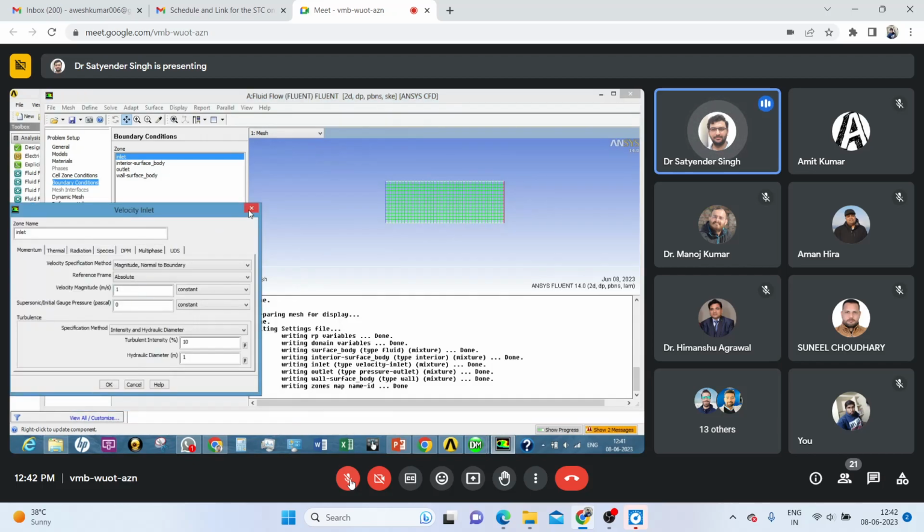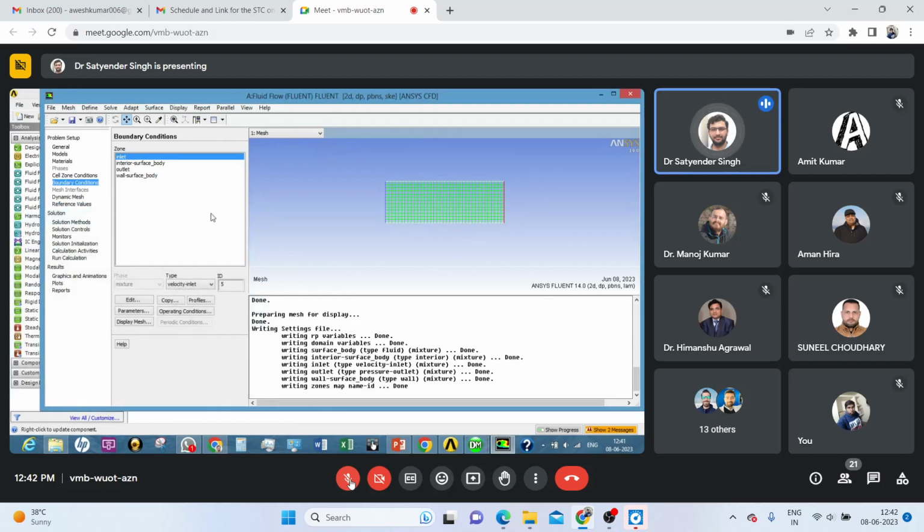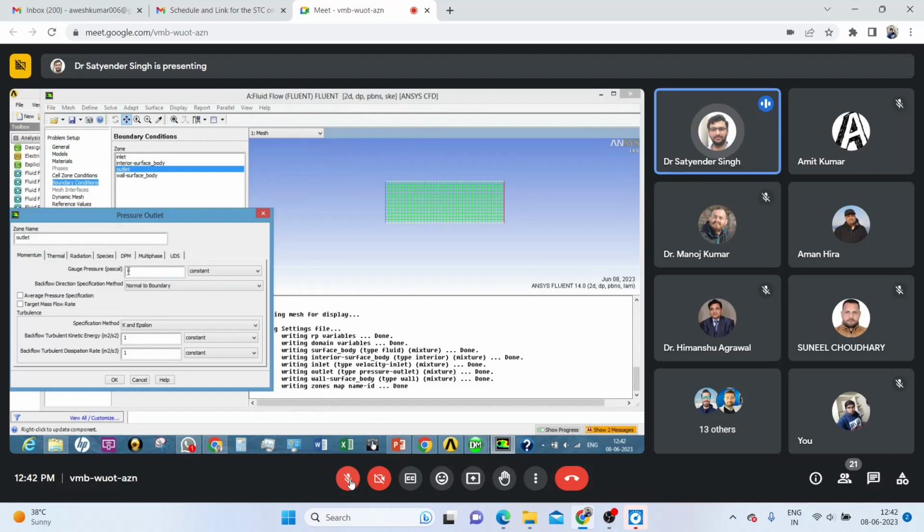We can assign value only to the velocity or in terms of pressure there, because this equation, let's say for u velocity, contains pressure as unknown. If I solve that for pressure, then it will contain v velocity, u velocity as unknown. So this equation can only give one solution at present. So for outlet, we are going with the pressure outlet. So pressure P0 we are assigning.